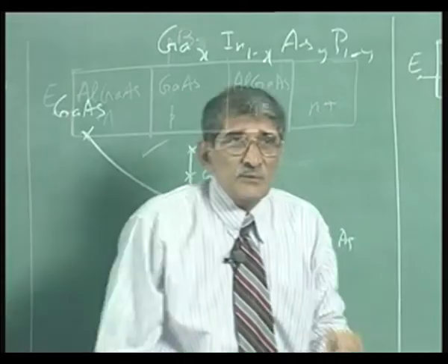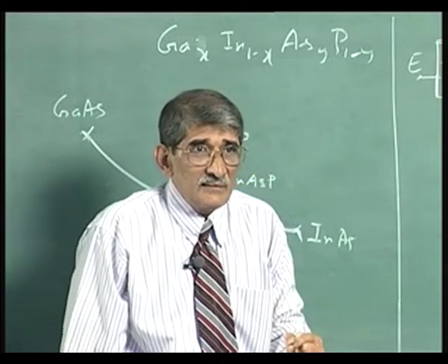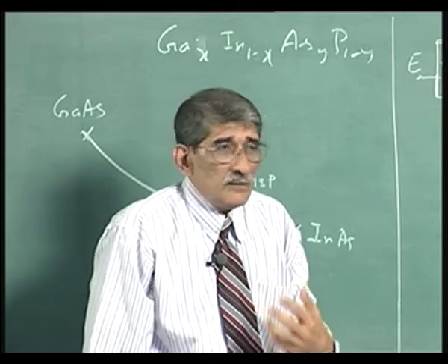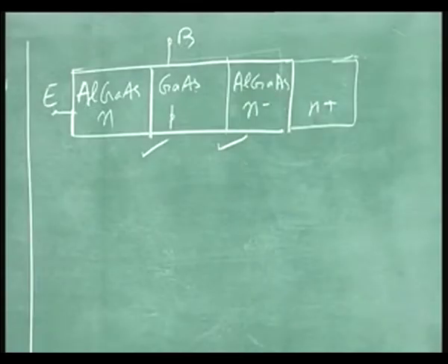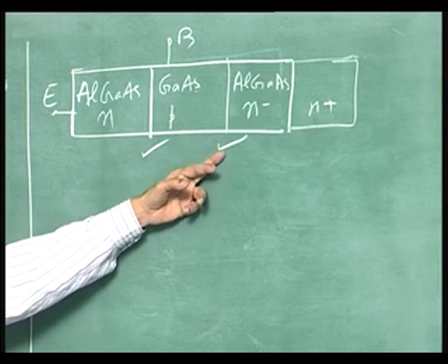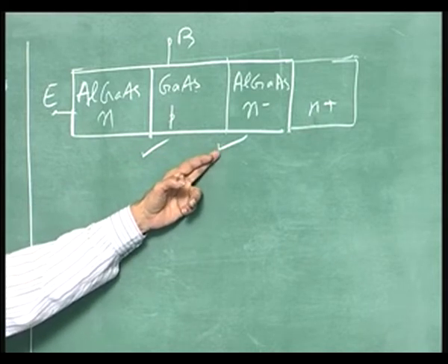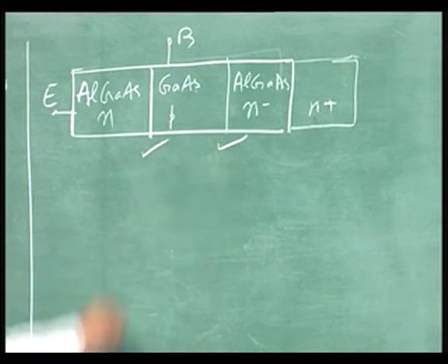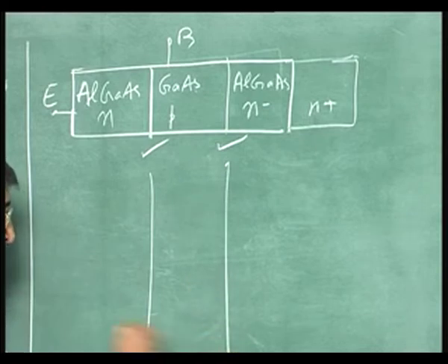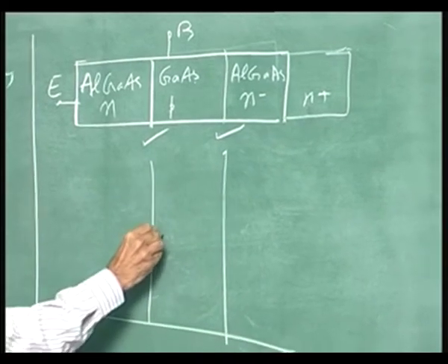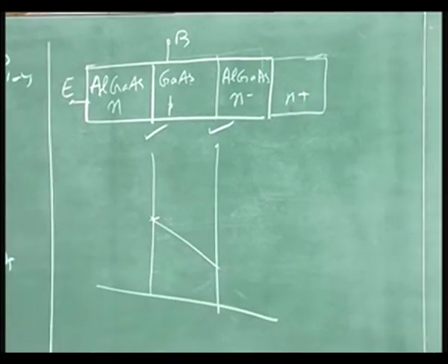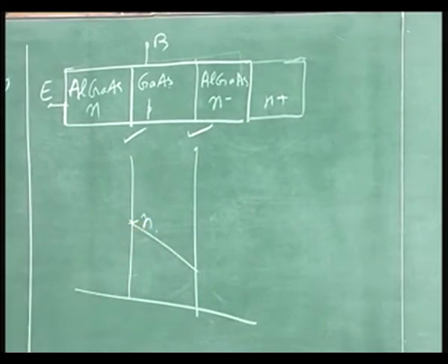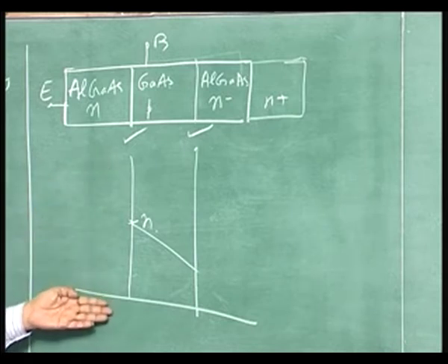But if the transistor goes into saturation, as in switching circuits, if you are not using ECL, then in TTL and structures like that, the transistor goes into saturation. The collector base junction gets forward biased. If the collector base junction is forward biased, what happens? You have the carrier concentration like that, stored charge there, this is the N. And of course, here you have hole injection.